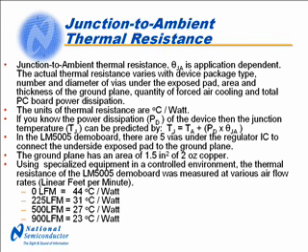The next few slides will detail several aspects of thermal design. Junction-to-Ambient thermal resistance, theta JA, is application dependent. The actual thermal resistance varies with device packaging type, number and diameter of vias underneath the exposed pad, area and thickness of the ground plane, and the quantity of forced air cooling and total PC board area. The units of thermal resistance are degrees C per watt.